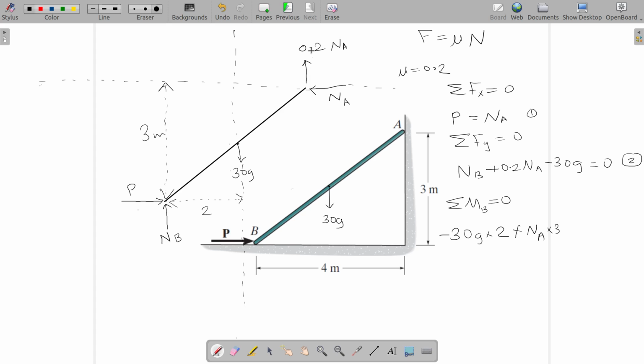Now you have remaining force, this one. So the line of action of 0.2 Newton, 0.2 Na is this one. The perpendicular distance between this line of action and this point will be this whole distance, which is 4 meter. So 0.2 into 4 meter. Now what will be the sign of this one? This force is tending to rotate the bar in anti-clockwise direction. You can see that it's trying to rotate in anti-clockwise direction, which means this is again positive.